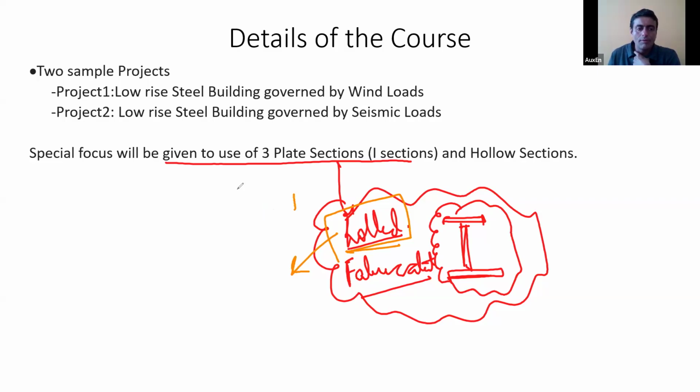And for many of the uses, you are not able to achieve economy if you are using rolled sections. They may be very good against the effects of earthquake, but they are not optimized for your general locations where you don't expect earthquakes to strike quite often. So rolled sections may not be the best and most optimum sections that are available, hot rolled.